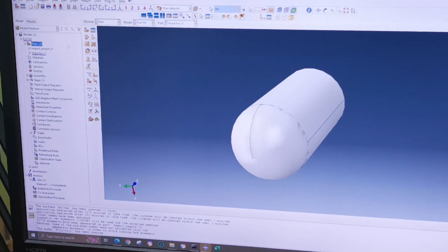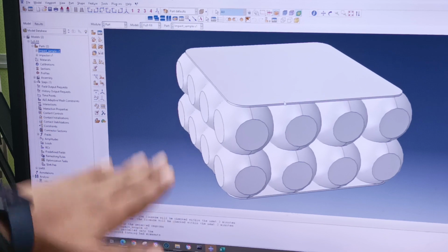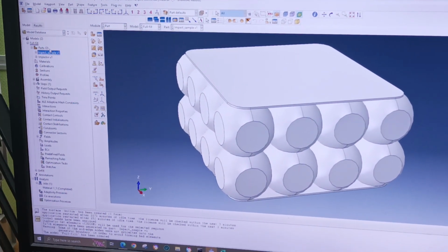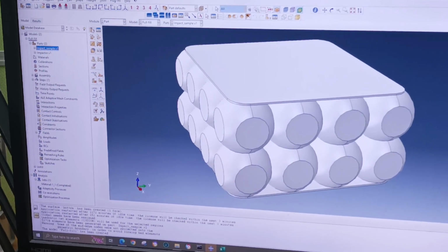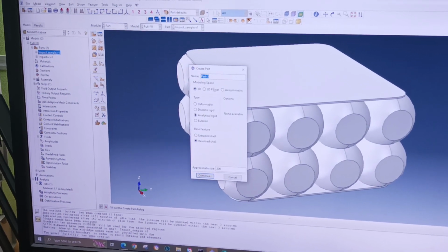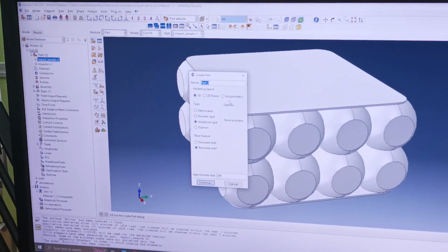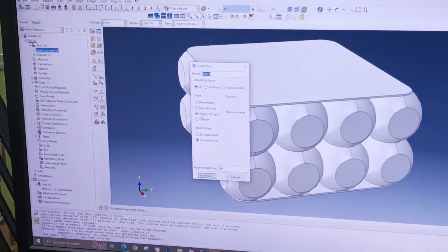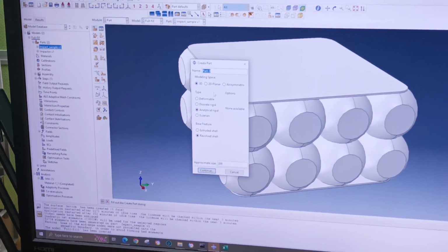Another thing is, now we have the sample. We need a base to keep the sample on top. So we need to make the base here. The way I told you, you go to create the part. You click on create part, and then we have many different kinds of systems: 3D, 2D, axisymmetric, and in the type we have deformable, discrete, analytical, Eulerian. These are the kinds of parts we can make.